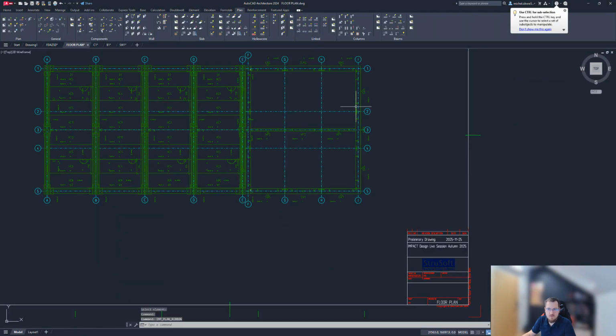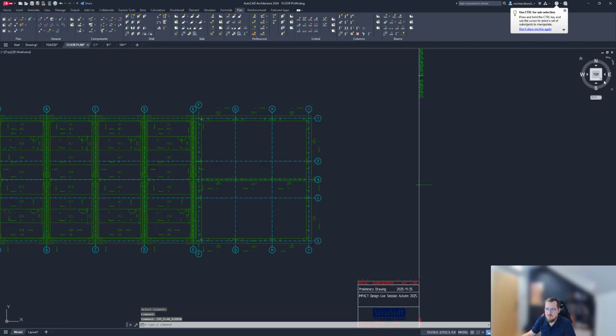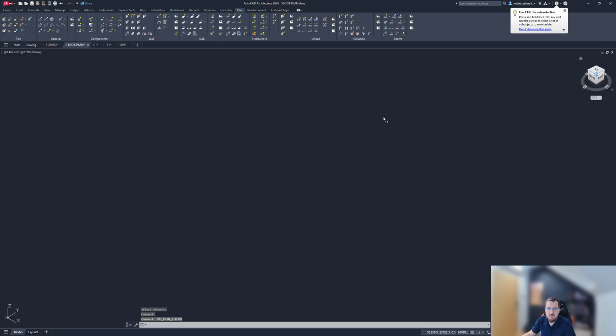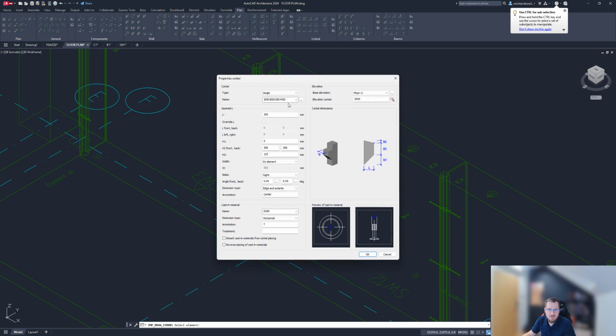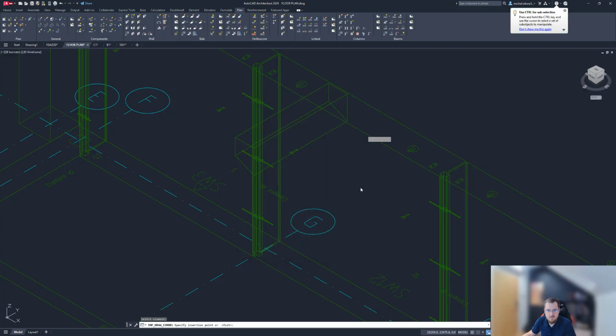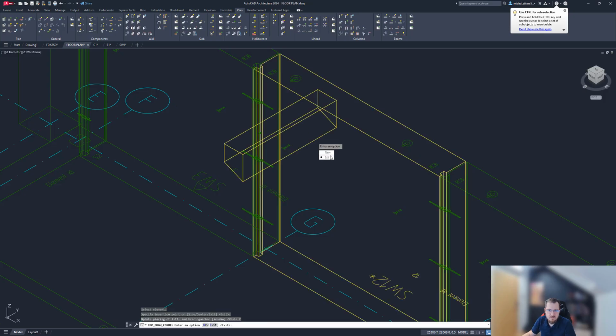Let's go to floor plan, and let's finish about that one last feature that I don't think we've ever shown. We can actually add corbels to walls. Let's draw corbel. Let's do that. And maybe not at this height, but let's 50. Width, let's go fixed width, let's go 50. And like that. Let's go. Oh, that's the wrong side of it, but yes, let's place that.